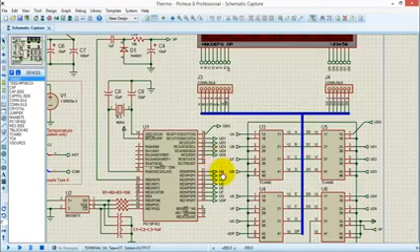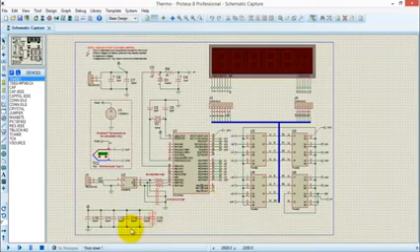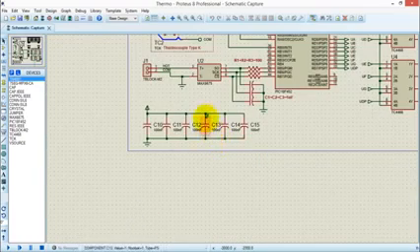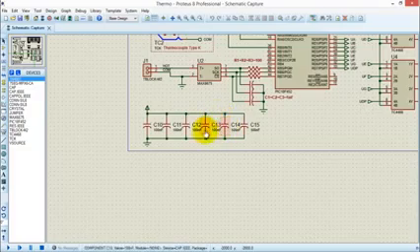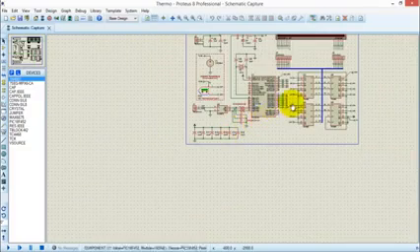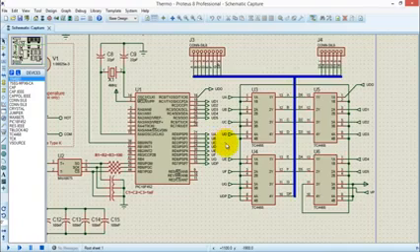The connection can be made by two different methods. You can directly connect different components through the wire, or you can use the terminal. But remember, for ground and supply, you must use the power terminals in order to properly identify the trace in Proteus Aries. So let me demonstrate.